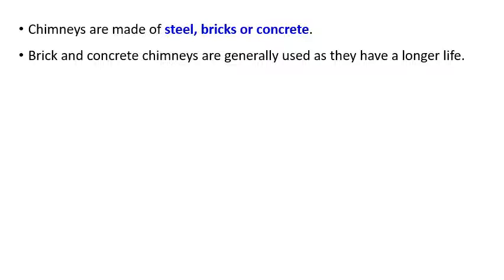The flue gas produced may be sulfurous in nature. When we are giving excess air, the sulfur dioxide will become sulfur trioxide, and because of the dew point in the chimney, this water with the sulfur trioxide will become sulfuric acid.